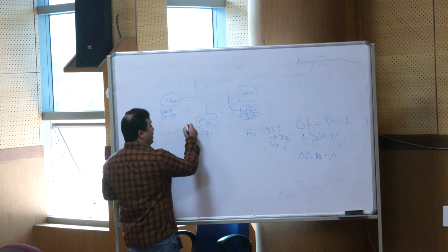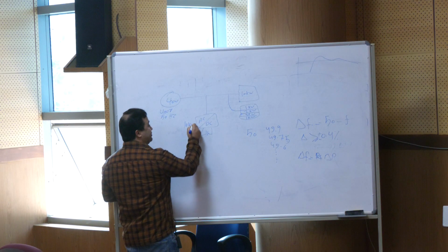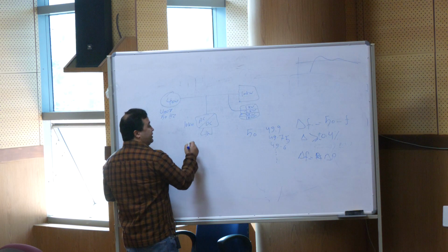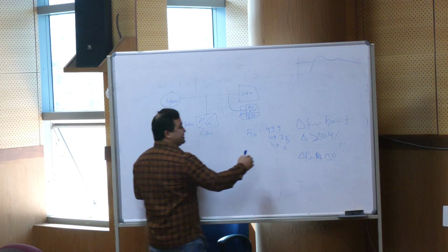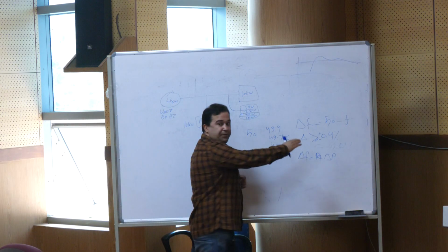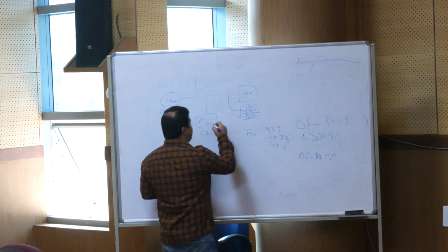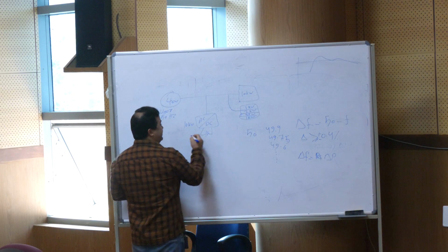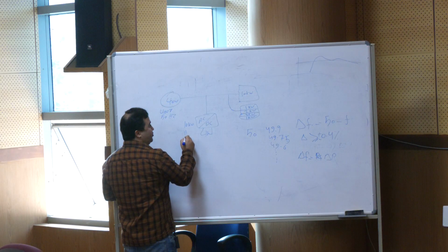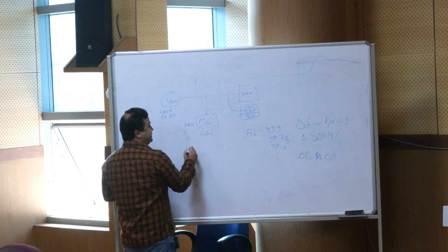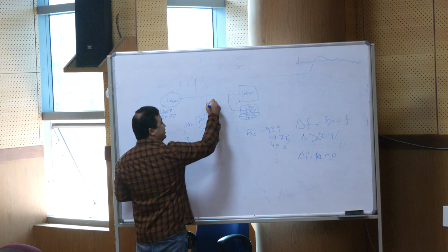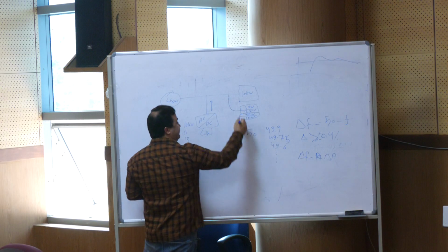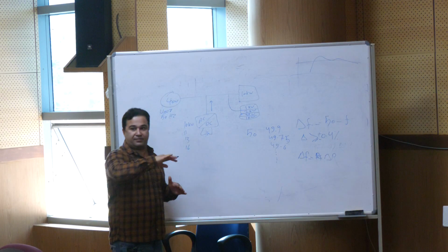If, for example, now we inject 10 kilowatt, it should increase. Why? Because the frequency is dropping. So by this, we increase the value. In this stage, it can be 11 or 13 or 16. So we increase the power injected to the grid. Then we fix the frequency again to 50.